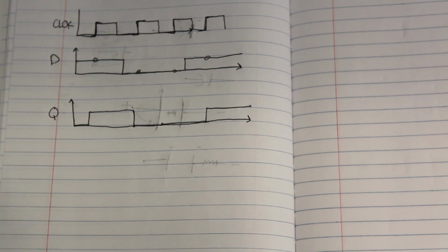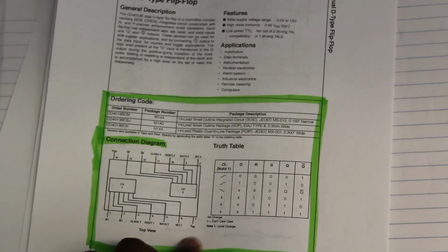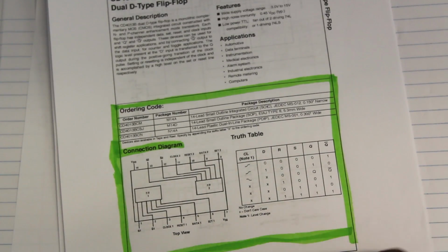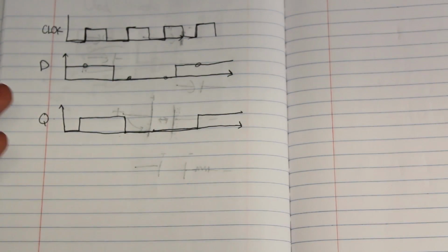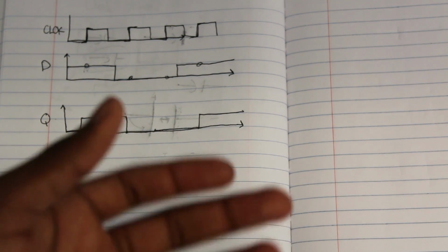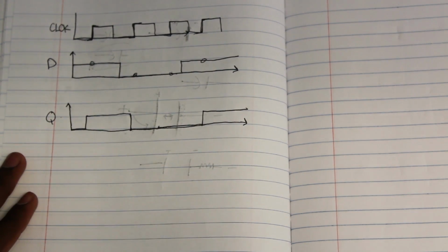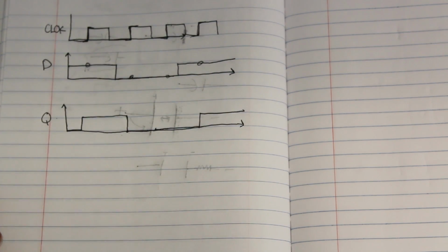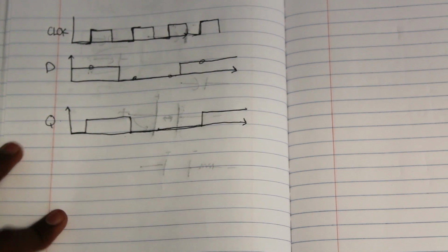And you can build this manually, right? Because on the flip-flop, they still have a set and reset. Like I said, this is the data sheet for a flip-flop. They still have set and reset. So you can do it yourself. You can build the inner workings of a flip-flop yourself with a flip-flop if you really want to, just not using all the enhancements that a flip-flop automatically comes with. But since they already come with all these abilities, all this stuff that it automatically does for you, this is why we use it, okay?